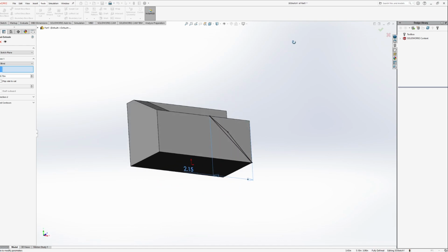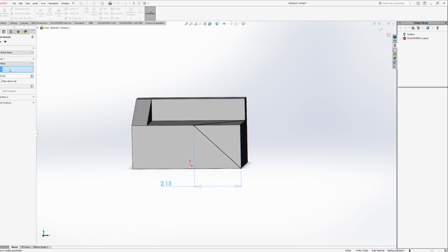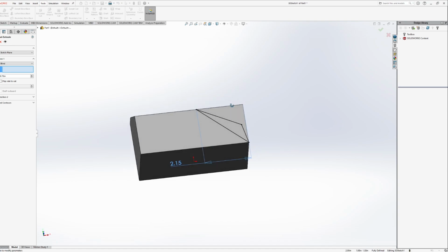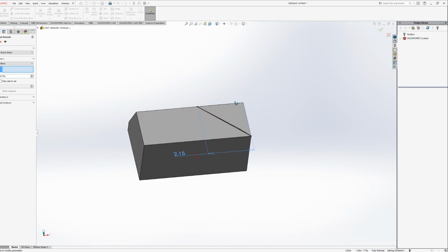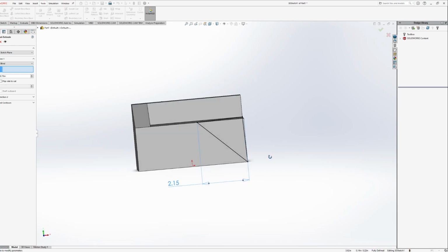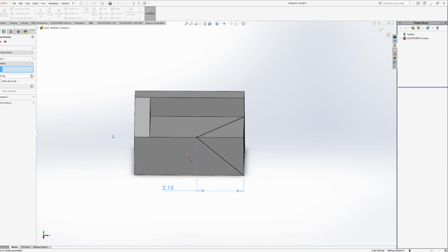And the reason for this is because SolidWorks doesn't actually know where to start extrude cutting from. Keep in mind, it has many directions that it could start this extrusion from, almost like if you're thinking about loft. It could start extruding normal to this shape, however, it could start curving to the left or to the right or in some other given direction. So we need to actually give it a direction, indicated by this blue box, to create this extrusion.